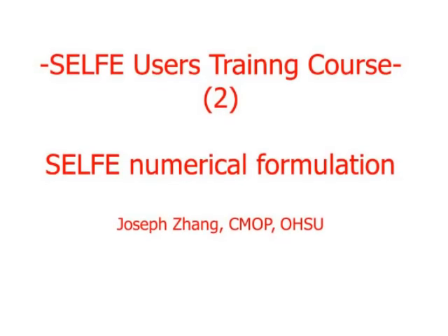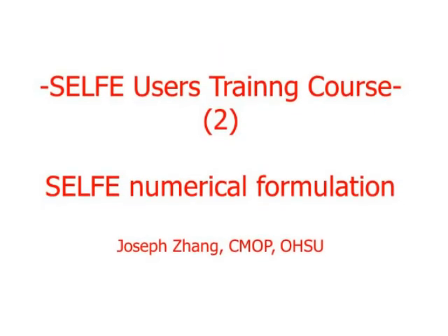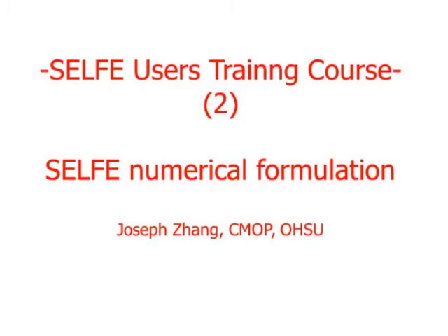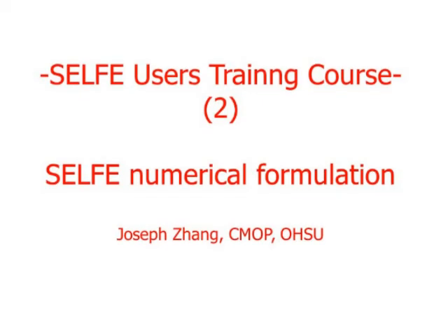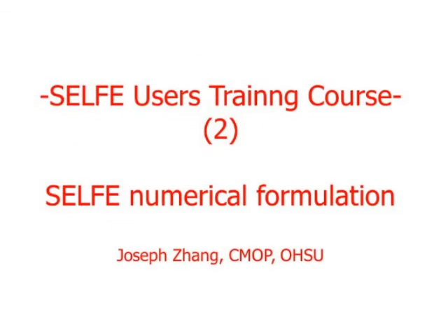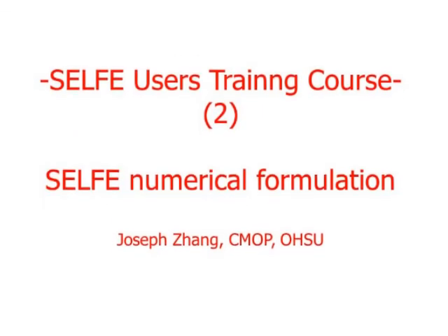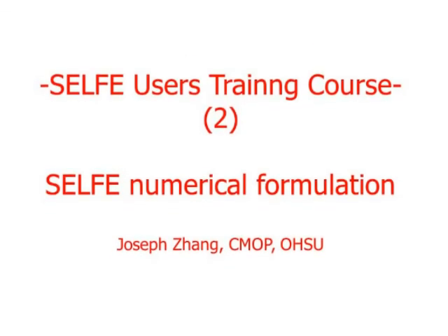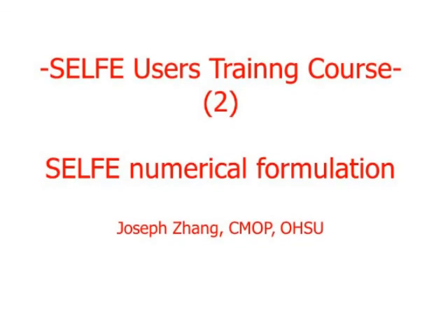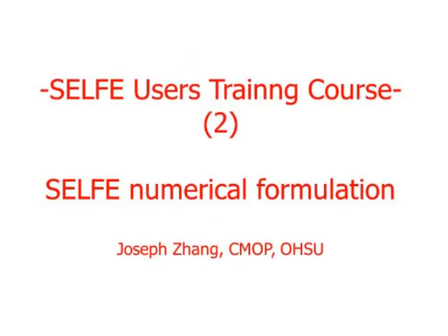But recently we found some perplexing problems with this GOTM library. In a shallow region, sometimes you get NaN coming out. I suspect it's a division by zero or an overflow or underflow problem, detected by the main SCHISM code. The funny thing is that it's really platform dependent.